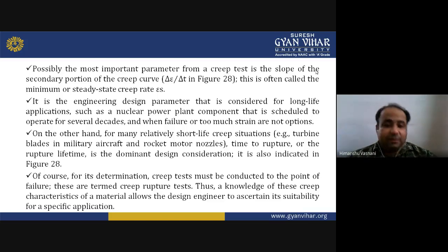On the other hand, for many relatively short-life situations like turbine blades in military aircraft or rocket motor nozzles, time to rupture, or rupture lifetime, is a dominant design consideration. Of course, for this determination, creep tests must be conducted to the point of failure. They are termed creep rupture tests.